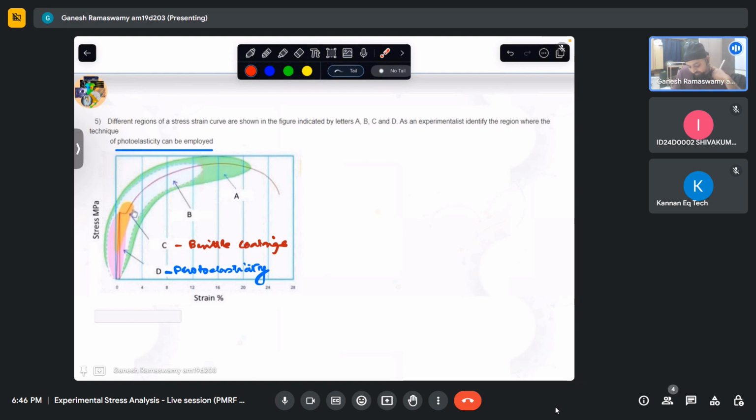There is a limit up to which it can go, because even the wires that you are using should not yield, because that is also getting loaded. So there is a limit to that. So for the strain gauge, of course, this limit should not be exactly read. These are just to give an idea of which range it is applicable in, so that we know when we are looking at some problem in hand and we anticipate that there is a particular level of stress or strain that we are testing this for.